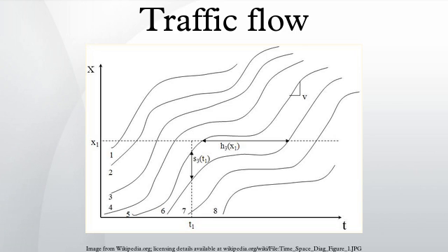Traffic bottleneck. Traffic bottlenecks are disruptions of traffic on a roadway caused by road design, traffic lights, and accidents. There are two general types of bottlenecks: stationary and moving bottlenecks. Stationary bottlenecks are those that arise due to a disturbance that occurs due to a stationary situation like narrowing of a roadway or an accident. Moving bottlenecks, on the other hand, are those vehicles or vehicle behavior that causes the disruption in the vehicles which are upstream of the vehicle.